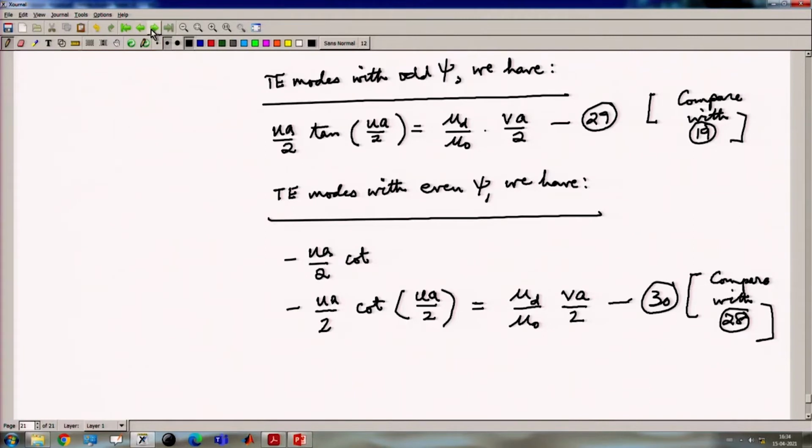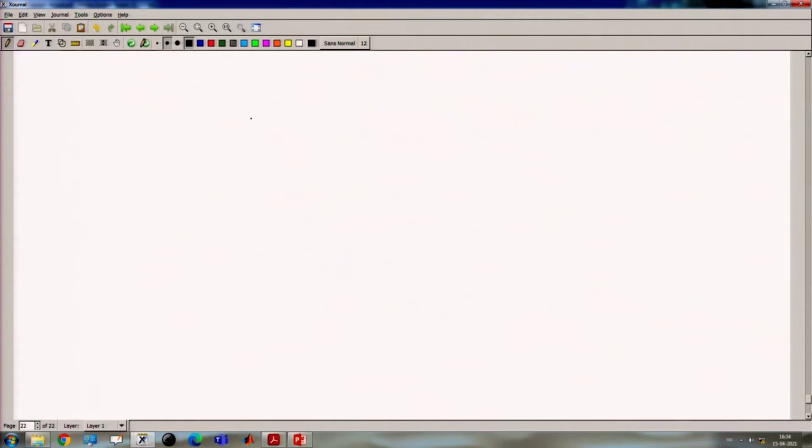So, for the TE modes, the fields are obtained from the psi's by the equations which are exactly dual to equations 4 that are relevant for the TM modes. We have already derived those equations, but these equations are for del y equal to 0 and del z equal to minus j k z as we did for the TM modes.